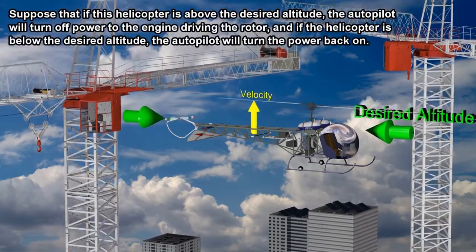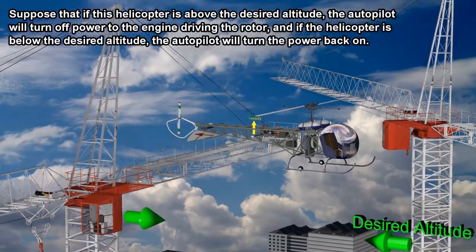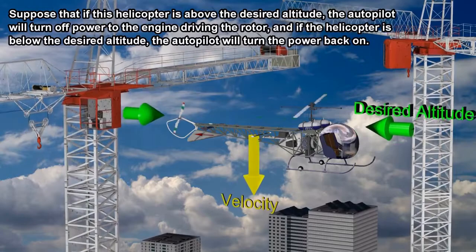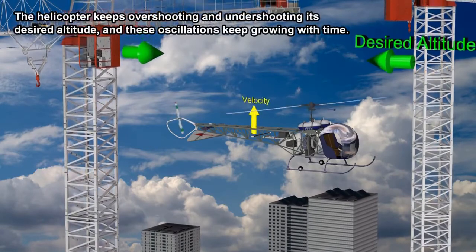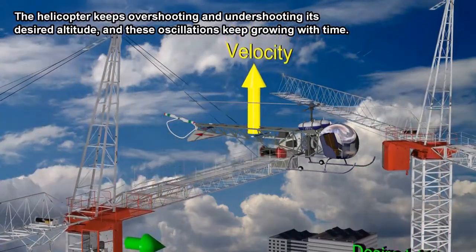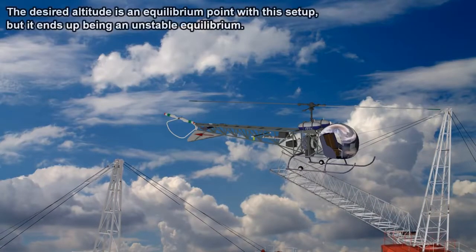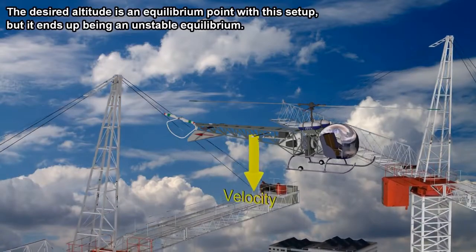Suppose that if this helicopter is above the desired altitude, the autopilot will turn off power to the engine driving the rotor, and if the helicopter is below the desired altitude, the autopilot will turn the power back on. The helicopter keeps overshooting and undershooting its desired altitude, and these oscillations keep growing with time. The desired altitude is an equilibrium point with this setup, but it ends up being an unstable equilibrium.